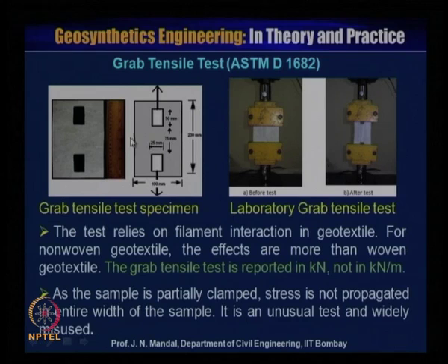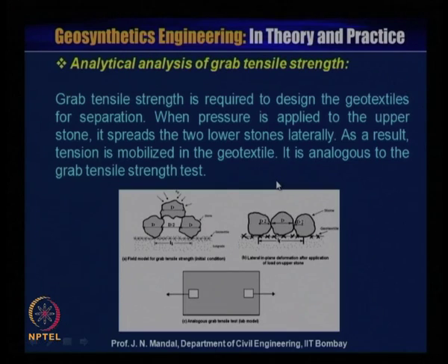Stress is not propagated across the entire width of the sample, only this portion. So, it is an unusual test and widely misused. Grab tensile strength should not be used as a design parameter. Now, we will address the analytical analysis of grab tensile strength.